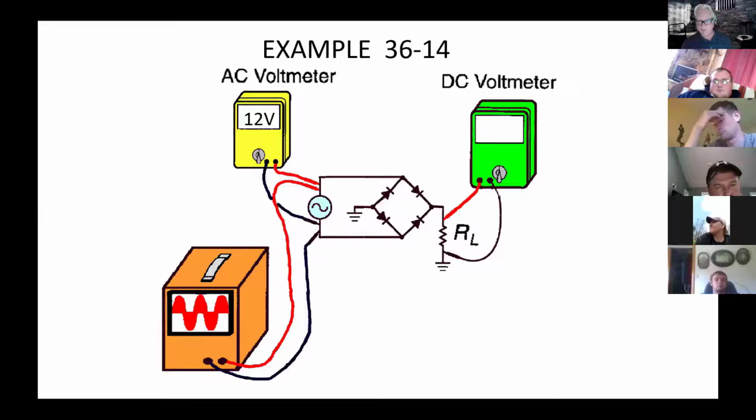So your power supply will actually have transformers with multiple taps, so that you're going to come out with 5 volts, you're going to come out with 12 volts, because different things in your computer require different voltages. And most of those have to have DC voltages and DC current. So there's also going to be rectifier circuits, diodes, for each of those, filters, and regulators.